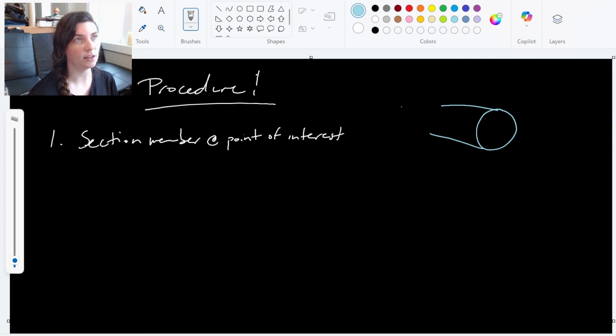So I have some beam or rod or something, and I take a section through it. And so this is my cutaway. This is the cross-sectional area I can see when I cut through it. And then you can see the rest going back towards the back there. So when I cut through that, remember I've got 6 different components here. We've got 3 forces and 3 moments. So a force in the Z direction, Y direction, X direction.